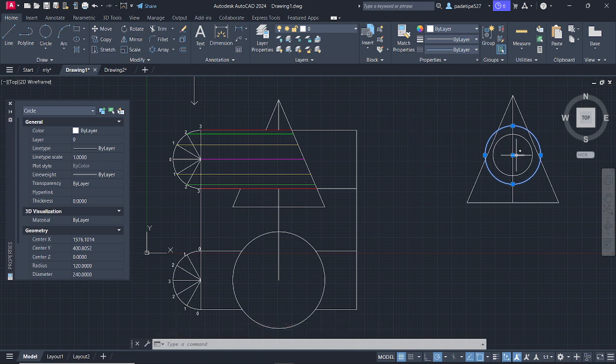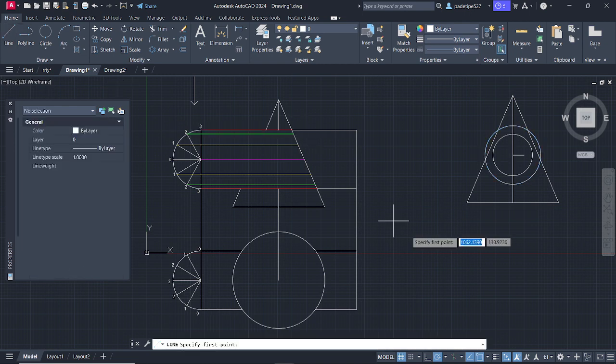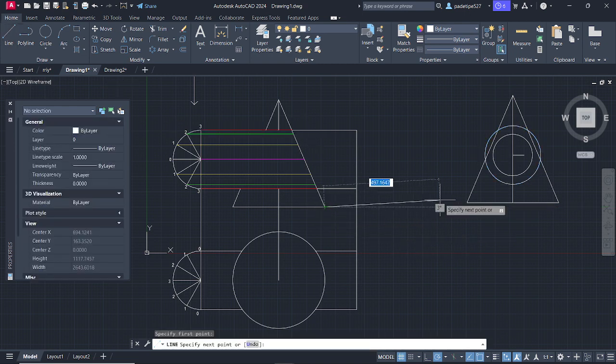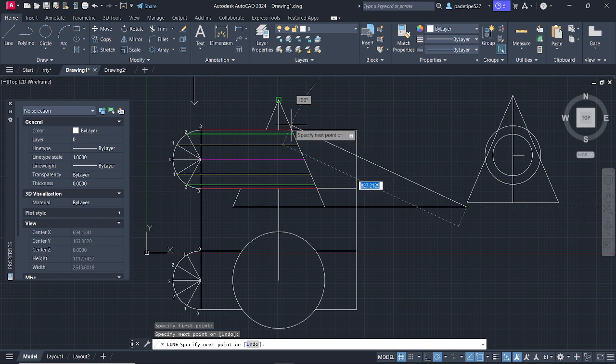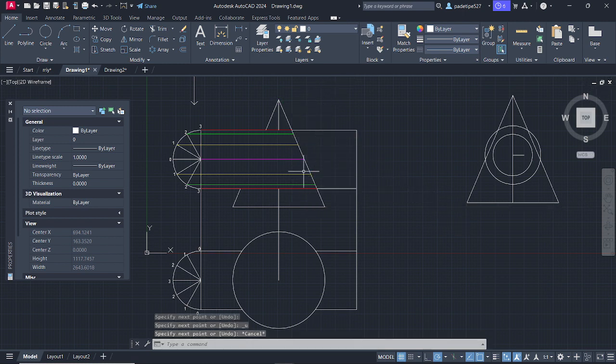We could have transferred it from this side view to this point, and as long as this part and this one are the same, they will still meet at this point, meaning you just have to extend this to this point, then start drawing your triangle from here. By the time you are transferring those lines, they will meet at all of these points too. Good. So we just want to use this one to avoid using the side view.